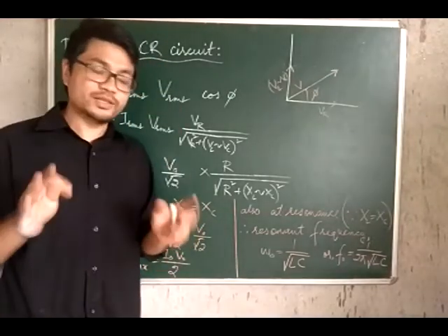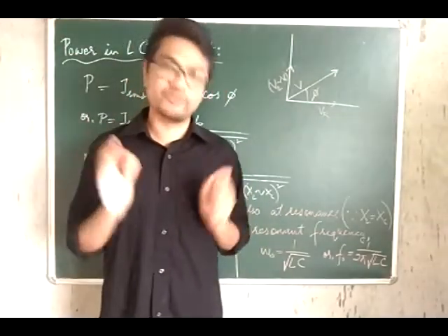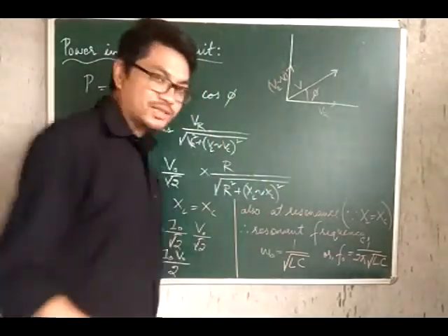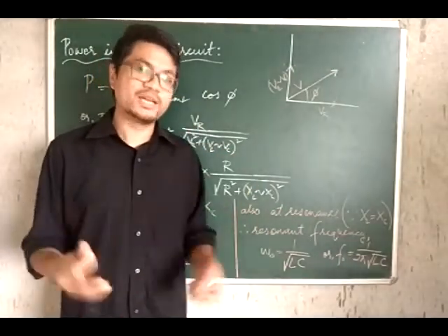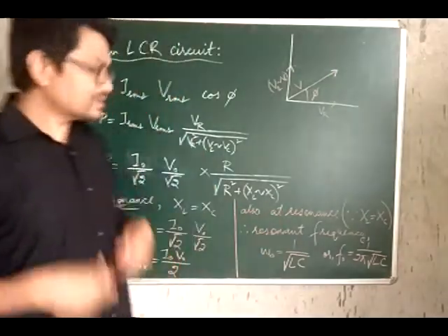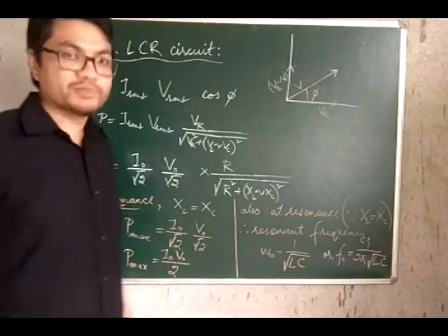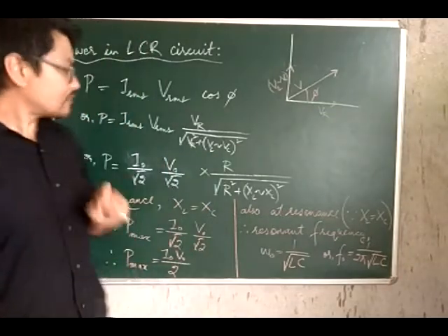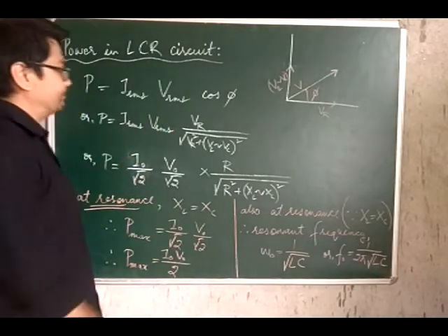If you check the video for the derivation of power, we started with the instantaneous value of power. Then we calculated for one complete cycle, and we saw that for one complete cycle sine 2 omega t was 0, cos 2 omega t was 0 and sine squared omega t was half. Since it was for one complete cycle, this P is also called average power, remember. I forgot to tell you that in that video itself. You can simply call it power, so to say.